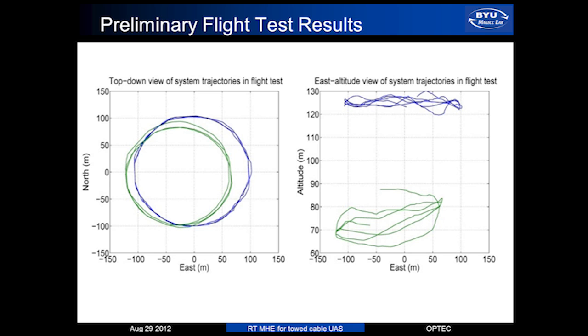The wind is coming from the east, so we can see the steady state orbit of the jog is shifting to the west. And in the side view, we can see that the jog orbit will not be flat anymore. It will be inclined. The deviation here is within 30 meters, so that is not good for the MAV to follow that inclined orbit.